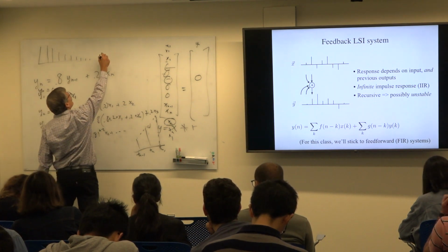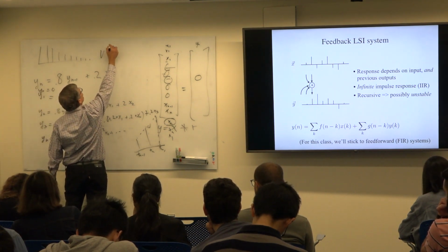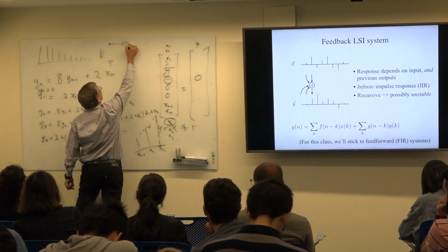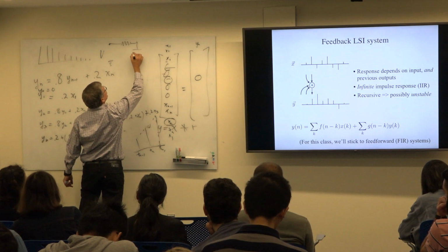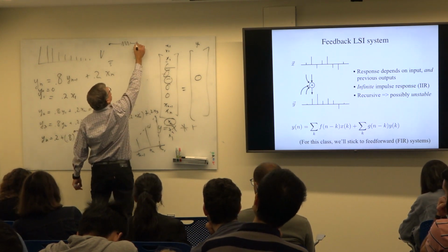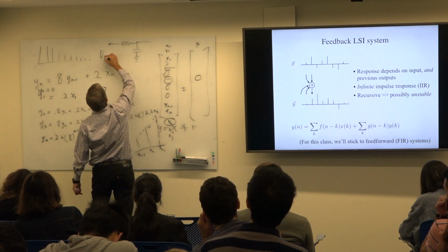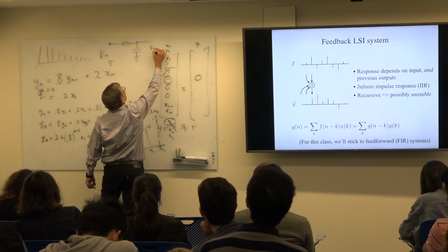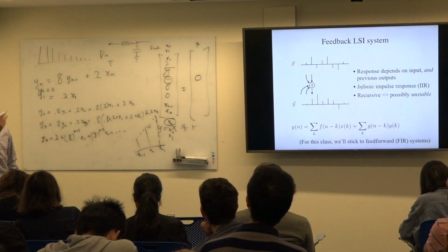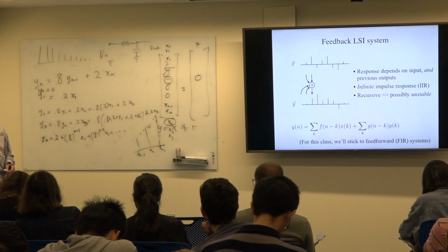If you have some voltage sitting here between this place and ground, and you put it through a resistor and a capacitor, which is just two parallel pieces of metal not touching each other, and you measure the voltage, so this is voltage in, and this is voltage out. That system, called an RC circuit, has an exponential impulse response, where the time constant, meaning how quickly it drops, is resistance times capacitance.